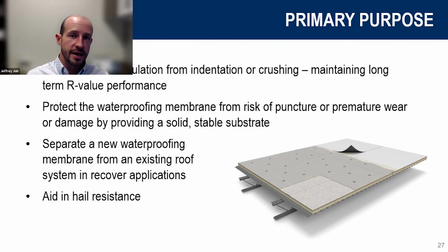In some cases, you might need what was often referred to as a barrier or some type of material in there to separate the insulation from that membrane, because there can be a potential for reactivity, or certain membranes don't necessarily function well with some of your styrene products. Typically, EPS can be somewhat of an issue. So adding that barrier board or cover board in there is going to allow you a nice, flat, rigid surface to then adhere or attach your membrane to. So that's another added benefit as well.